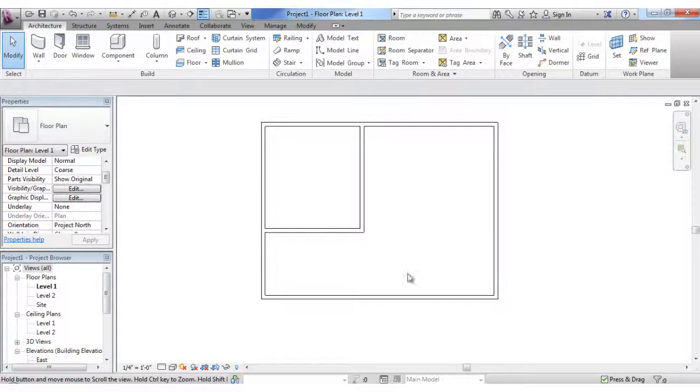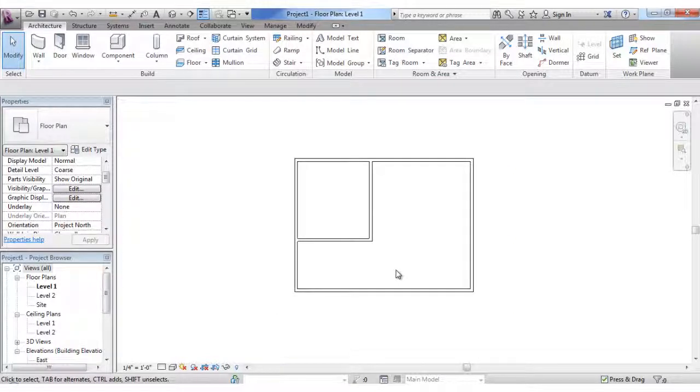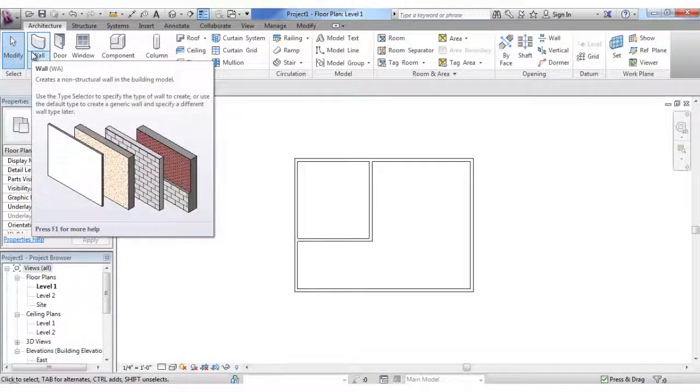Now, I'm not constructing anything specific here. I'm just actually adding some walls. Nothing important, okay? But this could possibly be our kitchen for this tiny little space, although that's an awfully big kitchen for a tiny little space such as this. But we'll assume that this is going to be some sort of space, and we'll leave that as it is. But that is how you're going to start adding walls. Okay, and we'll get more specific when we get into our own project, but this is where you find and add your walls. You're not drawing lines that you're going to then connect and turn into walls. You're actually drawing walls.